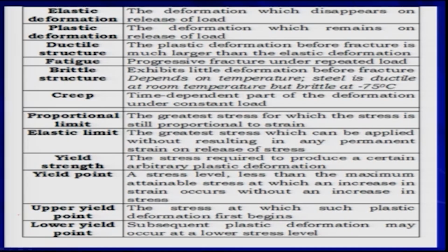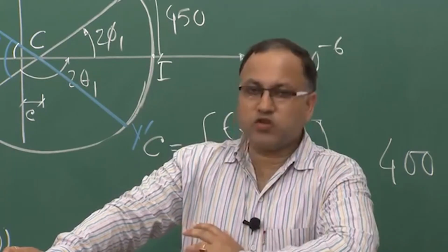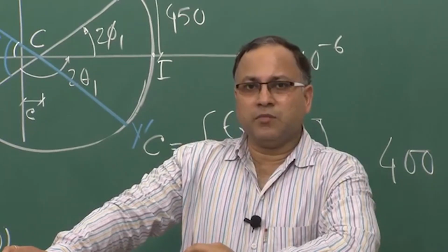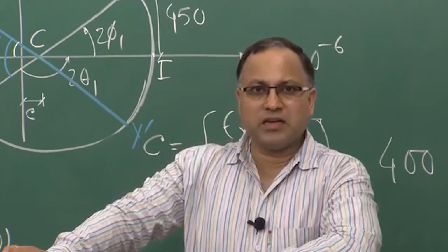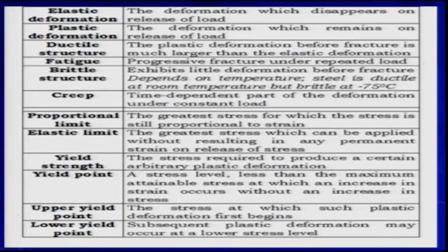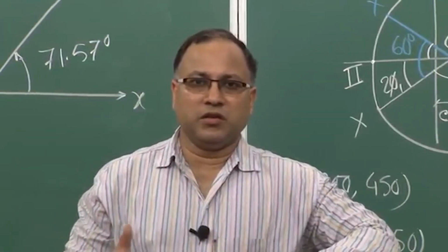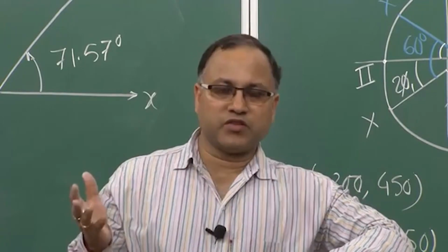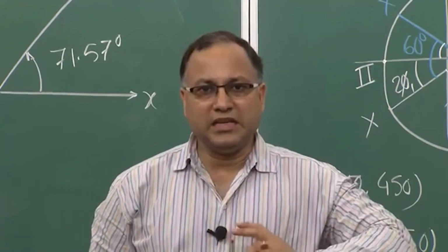Now, coming to the yield strength. This is very important, because you should design whatever material you are choosing for any structure. This yield strength is very important, because you should know when the strength of the material will go to the threshold value of the elastic limit. So, this yield strength is defined as the stress required to produce a certain arbitrary plastic deformation. Some amount of plastic deformation, if it shows, the strength at that point is known as yield strength.